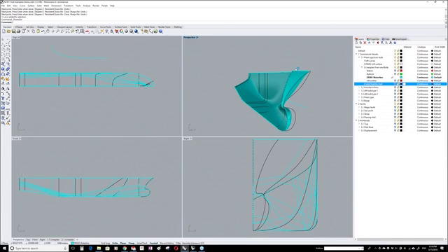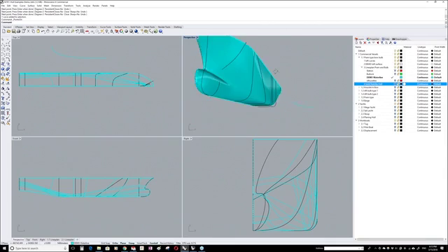The reason that we teach this rapid hull modeling methodology based on loft curves is that you have sort of a simple DNA because you have a set of curves, and then you create a surface out of them. So this is not better than doing direct control point modeling on the surface control points. It's just a little different approach that has pros and cons.